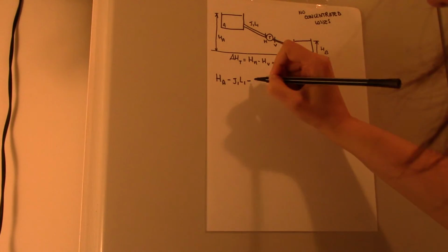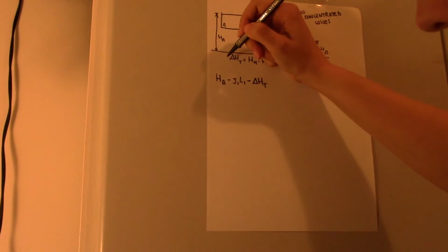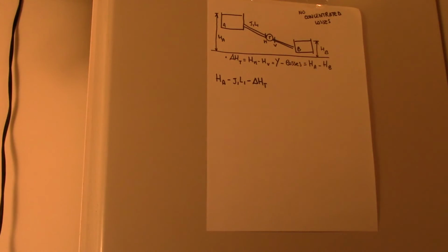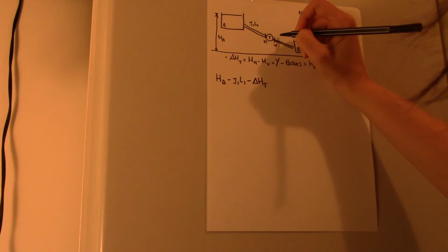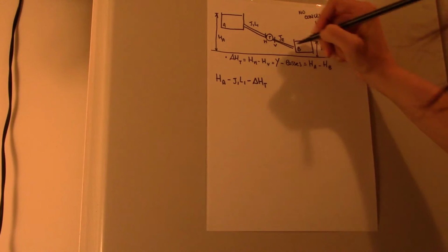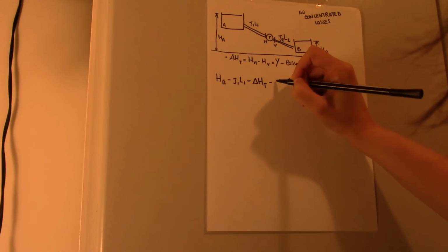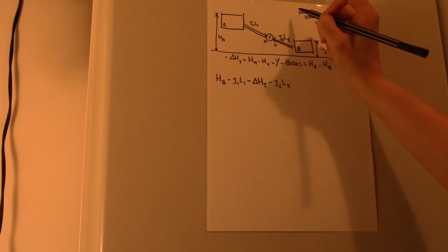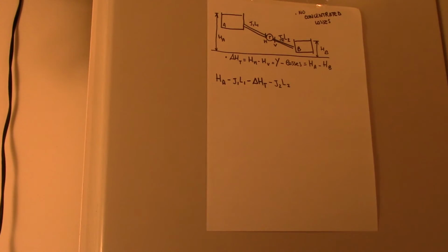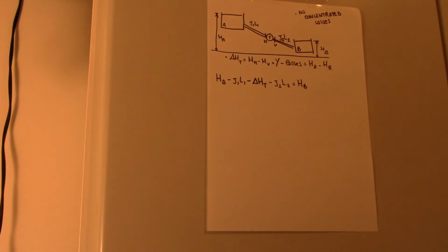So you will have minus delta HT, which is exactly what we have found before in your slide. Then you have again a decreasing due to the presence of distributed losses along the pipe number 2, then you have minus J2 L2, and everything, just consider that you don't have concentrated losses, is equal to HB.